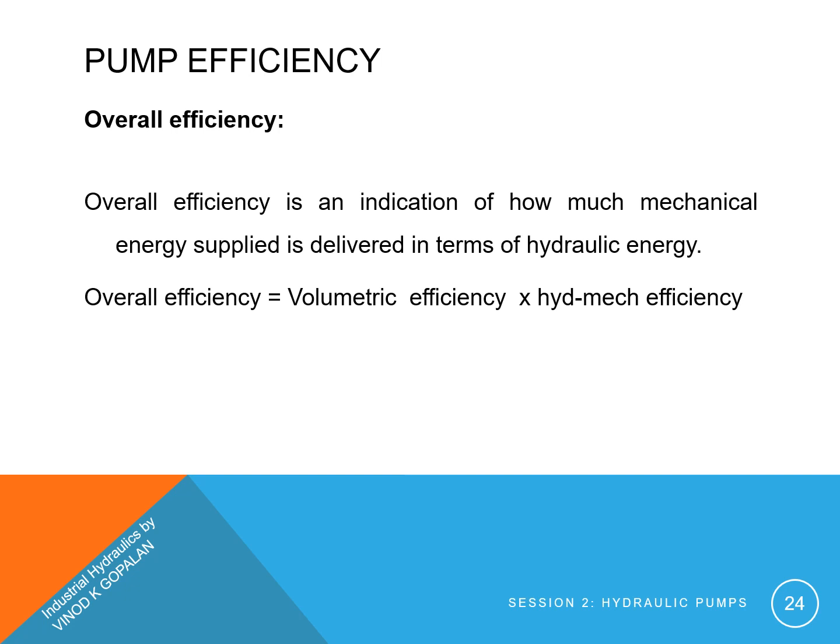Overall efficiency. Overall efficiency is an indication of how much mechanical energy supplied is delivered in terms of hydraulic energy. Overall efficiency is equal to volumetric efficiency times hydromechanical efficiency.